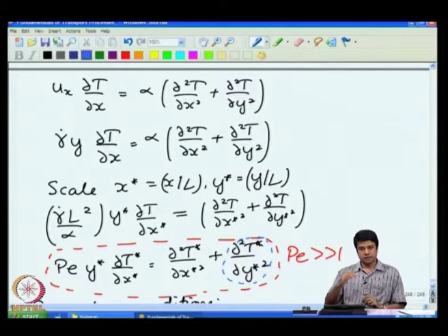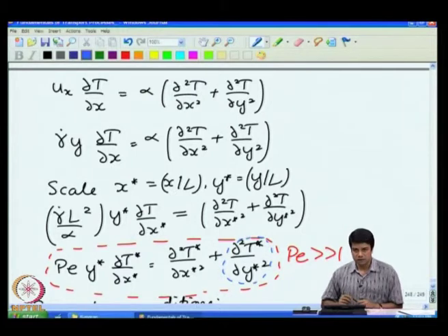So, there is no relative motion between the fluid and the surface, and because of that there can be no net transport perpendicular to the surface due to convection. Any transport perpendicular to the surface has to ultimately take place only due to diffusion. So, because of this physical reason, because we have neglected diffusion perpendicular to the surface, there is no transport of heat, and consequently there is no heating up, no change in temperature due to the heated section, when we neglect the diffusion terms.